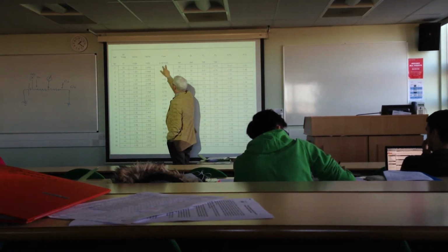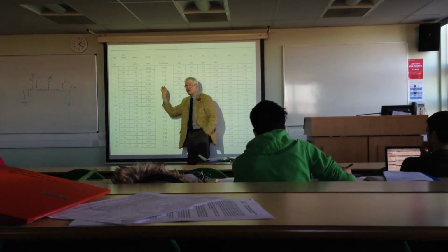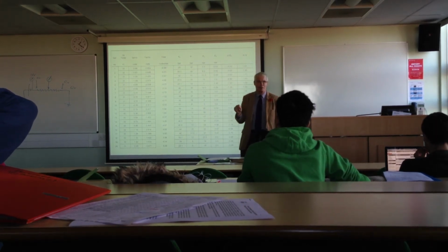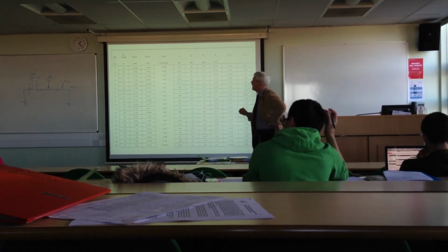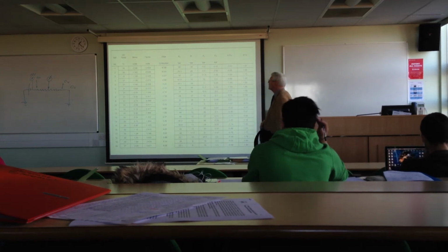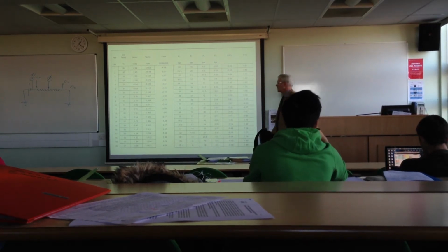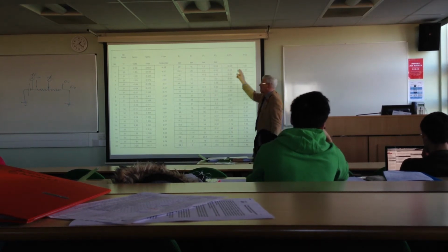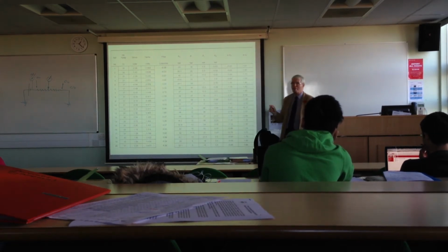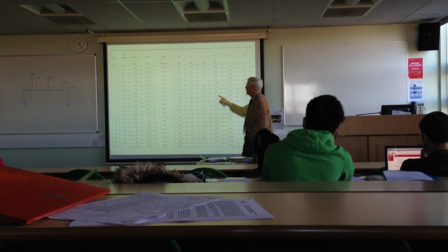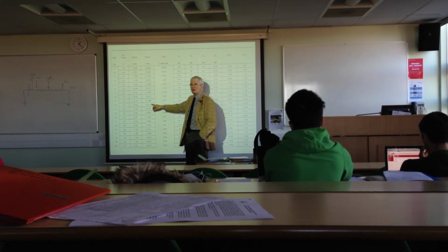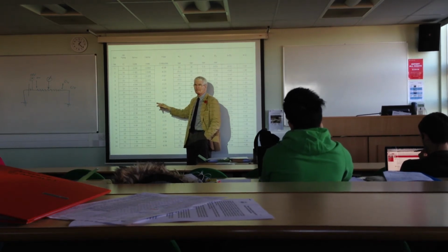These were the two columns, and if you hover over this one here, for the voltage, sorry, if you hover over that, you can see the calculation that's embedded. I want you to check that, write it down in your results, and make sure you understand how we've calculated that flow rate. And it goes from about -6 to +6 litres a minute on most of the ones we've done. Okay, you got that. And then we recorded the pressures and worked out the logs. But of course, this is the log of the flow rate. So if those two columns had swapped round and this one has swapped with it, then that column's not right. The other thing you can do is say, well, looking down here, that's a very, very low flow rate. That's because that's a very, very small voltage. So we know the motor's turning very slowly. Okay?